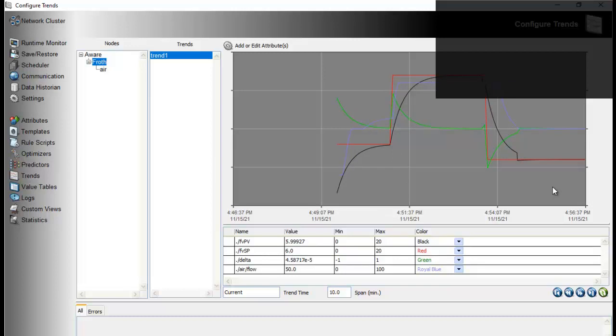Let's see. Okay, you see, it starts the disturbance. So we can put the scale 5 minutes, and you will see this is a disturbance effect, and immediately appears the error, and also immediately start correcting the airflow, reducing the airflow so that it can be corrected. So right now it's reaching, the process value is reaching the set point.